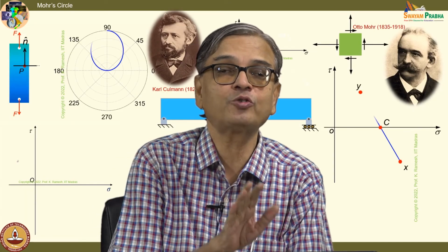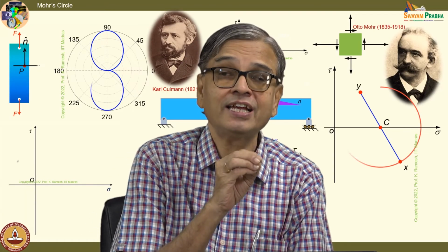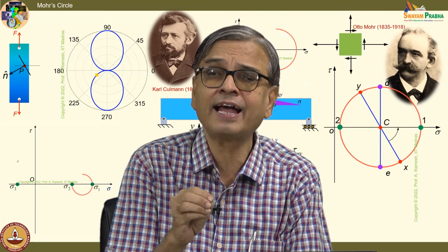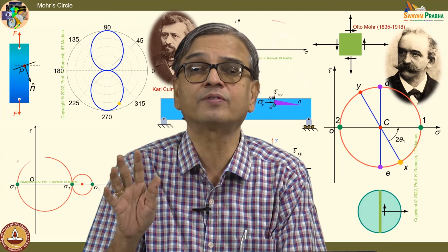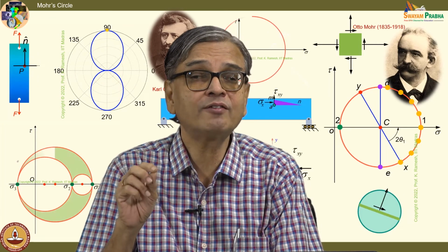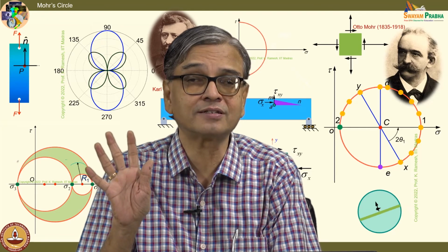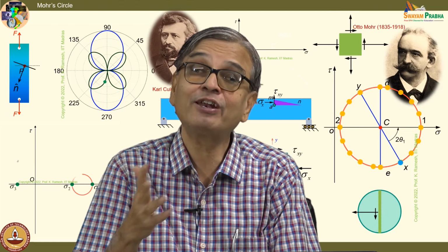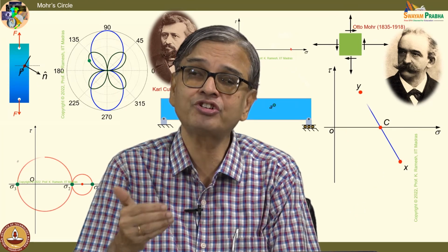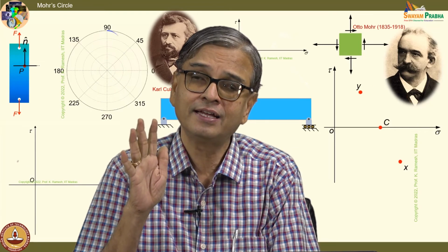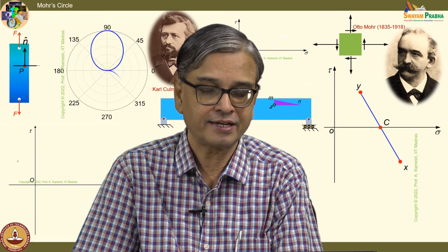And the knowledge what you have is, when shear reaches a maximum, you will invariably have normal stress also in a generic situation. In one situation, you will have normal stress is 0. What is that situation? We have just now seen. When I have pure shear, in the maximum shear stress plane also you will have only shear stress. Okay.